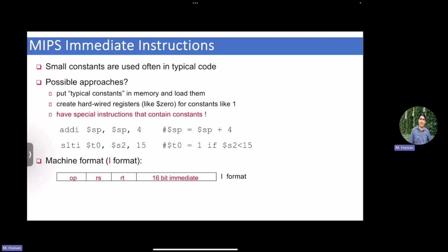But the general format is pretty much similar to the conditional branch ones, right? Again, I have an offset. Right now, I don't call this an offset because it's not an address, right? It's a general immediate value, it can be anything. And then I also have a source register and a destination register. If you compare this to the normal arithmetic, what did we change in the format? In the normal arithmetic add, for example, we needed two sources, one destination, right?